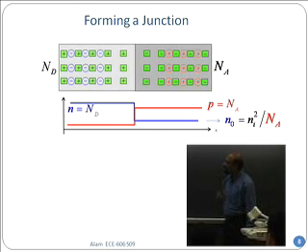Because when the next series of electrons further down wants to come, you can see on the acceptor side there are these exposed negative acceptor atoms sitting there, which say don't come anymore. Because now you have a bunch of negative charge sort of guarding the junction. And as a result, electrons will not be able to come anymore. And the same fate for the holes.